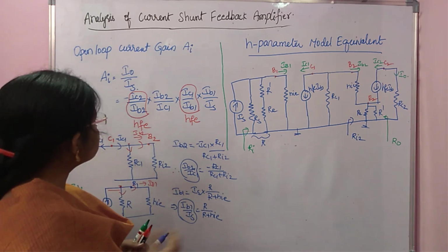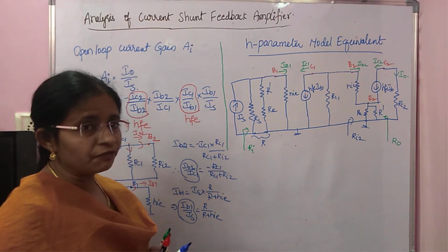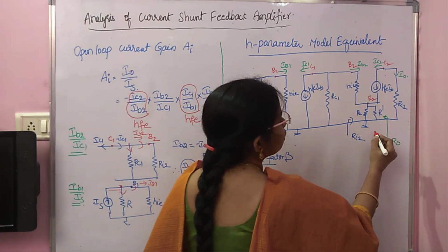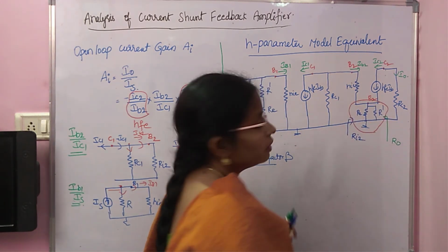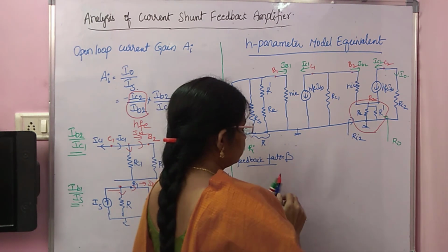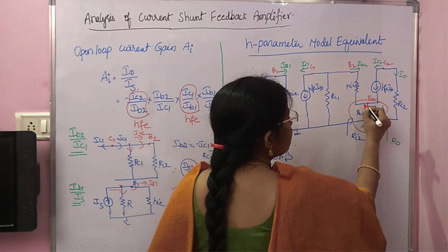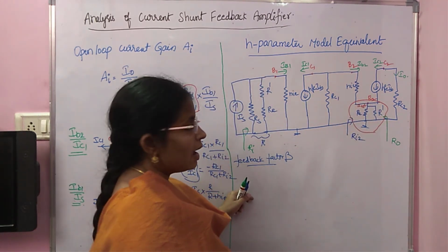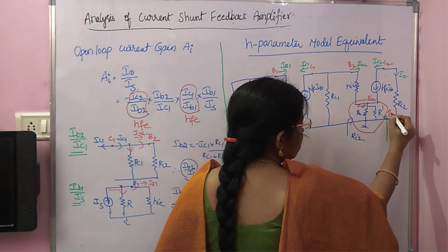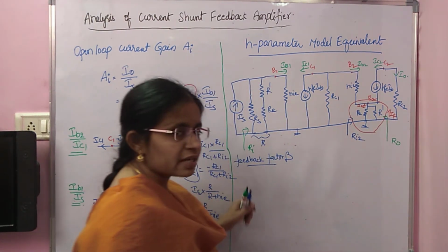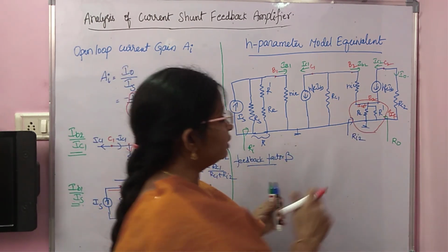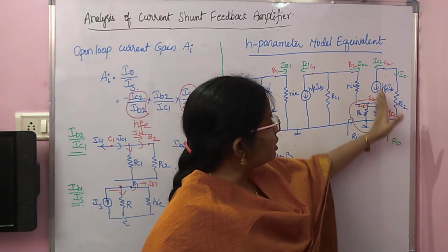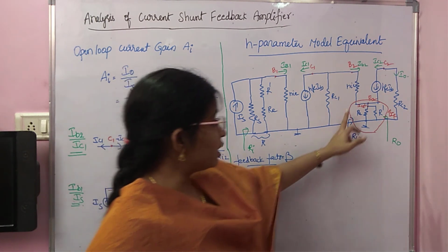Okay. Then what is the next step? You have to find the feedback factor beta. Now for this you consider only this part of the circuit. See this? That circuit is enough. So this is E2. From E2 the total current is IE2, let it be IE2, no problem. And through R dash, actually what is our current? You can verify the previous circuits, it is IF. Total current entering this node is IE2 and the current flowing through R dash in this direction is IF. So the two currents are in opposite direction.